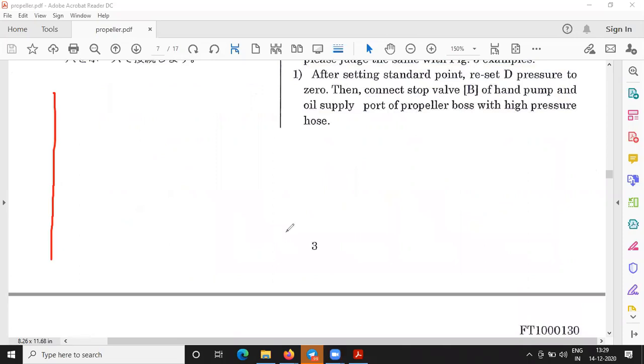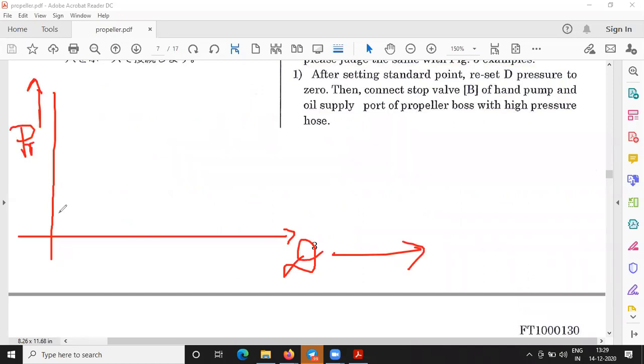Push-up pressure, this is distance. This is pressure. First we have given some pressure and it is at 0. That means we have given some pressure and it has not shown any deflection. After certain pressure starts increasing, it will start showing deflection because we need more force now to push it up. At 20, let's take 50 bar. We have given 50 bar and it has shown no deflection, the push-up distance is 0.